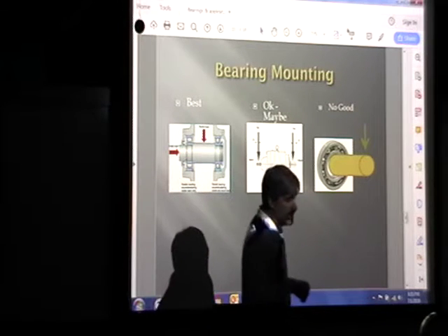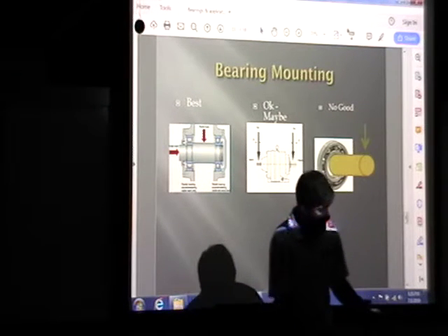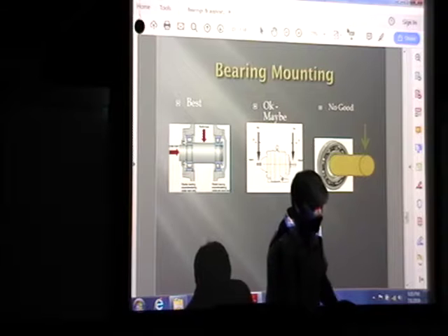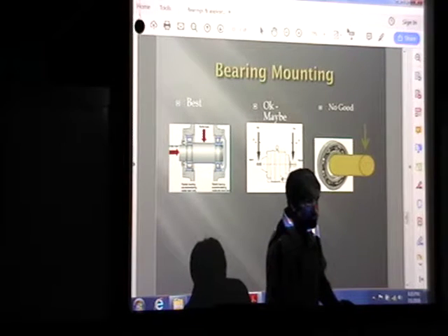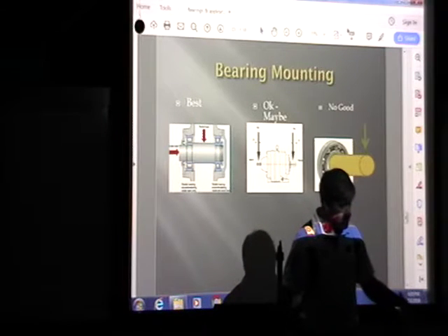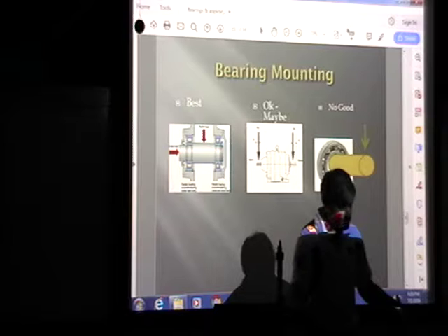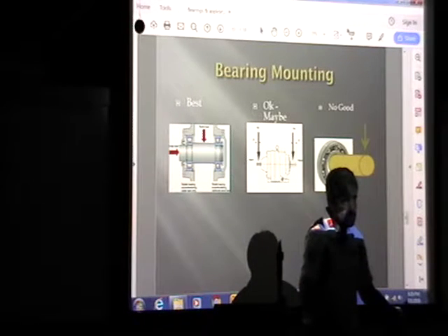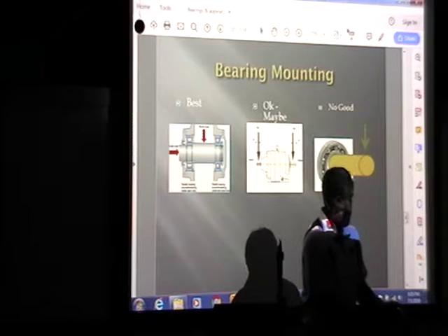When you start looking at bearings, there are clearances between the balls and the inner and outer race. You can feel with some of these, there's not much clearance there. This big one has very, very little clearance. So you can imagine by getting two of these bearings together, if they're off center, the shaft is going to want to run transversely or crooked, and that's going to eat up any power you might want to put in here.